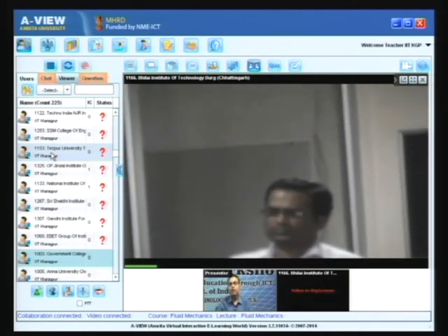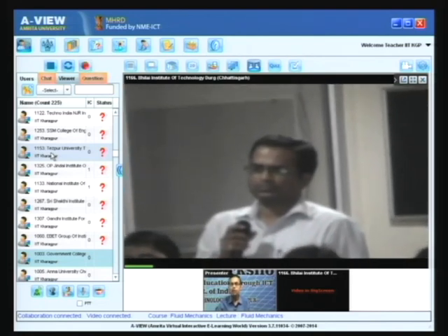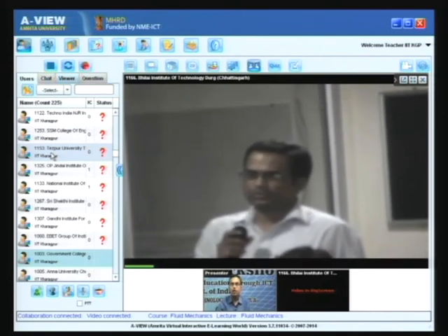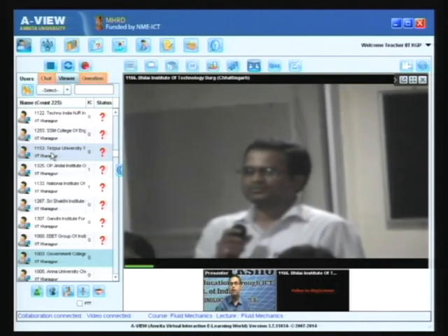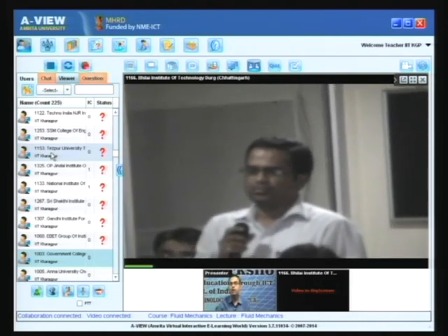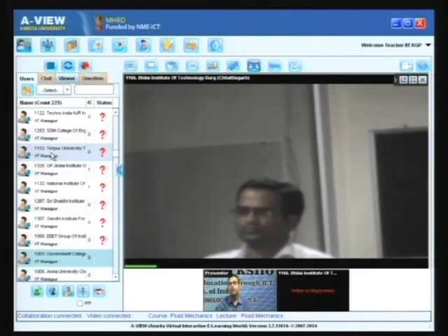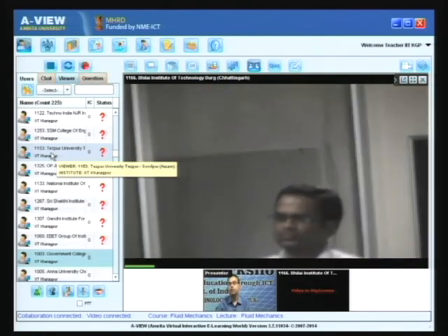There are instruments available, a particular instrument known as a goniometer. You can use the camera of the goniometer to take the image and then draw a tangent to the interface between the droplet and the surface. The angle between the tangent and the solid surface will give you the contact angle.